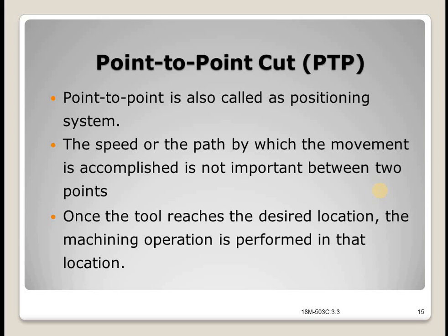PTP systems are the simplest machine tool control systems and are therefore the least expensive of the three types. However, for certain processes such as drilling operations, tapping, riveting and spot welding, PTP is perfectly suited to the task and any higher level of control would be unnecessary.